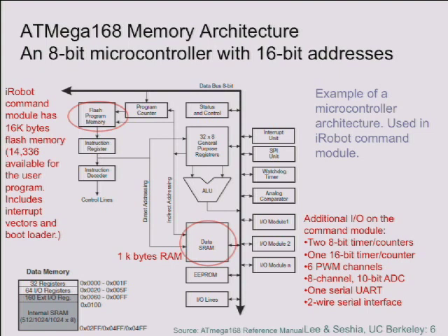The fact that we have 16-bit addresses is pretty convenient, because if we only had 8-bit addresses, we would only be able to address 256 bytes of memory, right? Okay, so we have 64 I/O registers. What happens if you overwrite those by accident? You change your outputs. So your robot could start doing crazy stuff, okay?